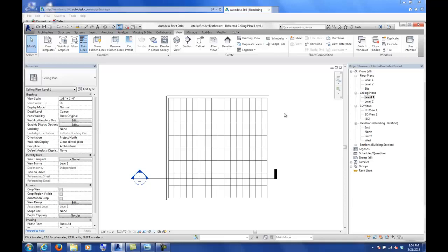That's how many lights you're going to have to place in order to get a realistic rendering, because Revit's going to actually read light data, and you can actually get real lights from manufacturers that are BIM lights or Revit lights that have true photometric lighting as part of that light. So when you bring in their light, you actually know how bright it's going to be within your space. So that's really nice. You can put in some lights, look at a space. If it doesn't look bright enough or it's too dim, you need to put in some more lighting somewhere and keep on working. So it's kind of a nice tool.